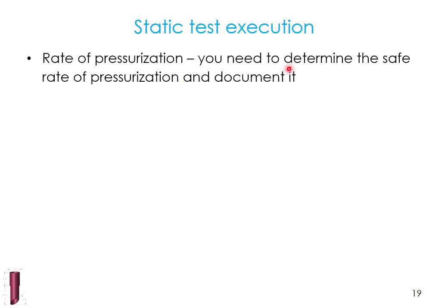When you're executing any static test, you want to think about the rate of pressurization. What's safe? If I'm pressurizing too fast, I can prevent metal stresses from equilibrating and can fail a pipe that wouldn't have otherwise failed.